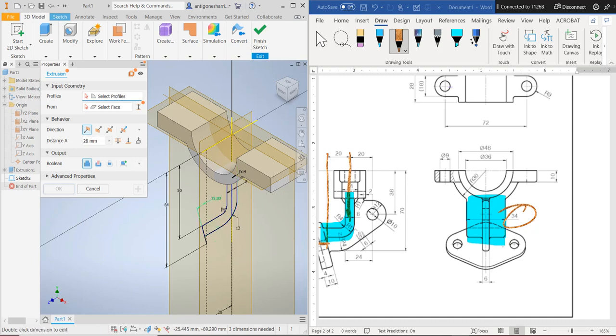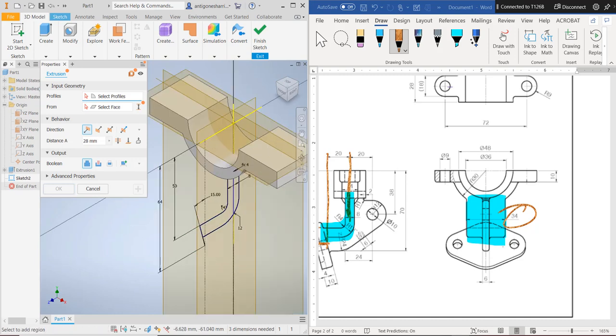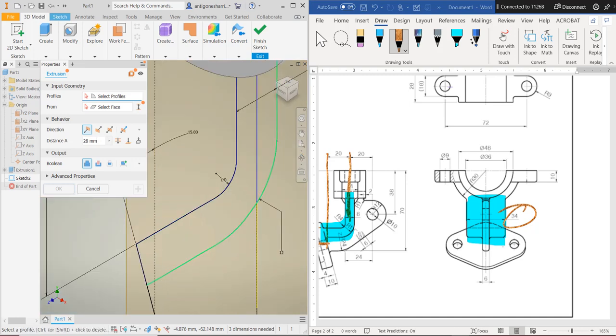See how it picks all these different lines? I, of course, zoomed in, but I need you to see what it did. Look what it did. It picked the front and not the back. You see how the field colors change? See that? That means that's what it's going to extrude. And you're going to be like, but why? And I'm going to be like, because that's a solid line. And you're going to be like, well, didn't you make that a construction line? I had put in a construction line, but there may have been a line in there anyways before my construction line. I don't know that because the software automatically puts in reference geometry. So please be aware of that.